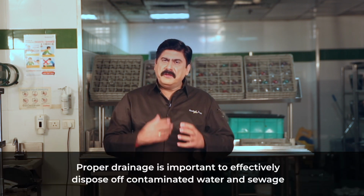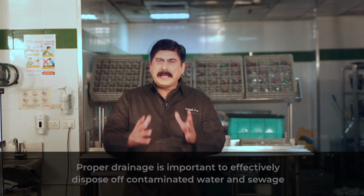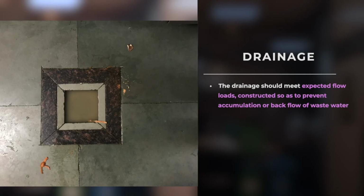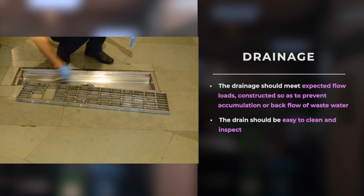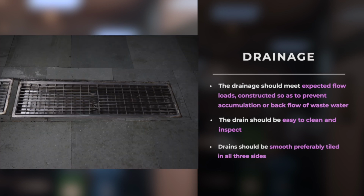To achieve the same, proper drainage is important to effectively dispose of contaminated water and sewage. The establishment must meet these requirements. The drainage should meet expected flow loads, constructed so as to prevent accumulation or backflow of wastewater. The drain should be easy to clean and inspect. Drains should be smooth, preferably tiled on all three sides.